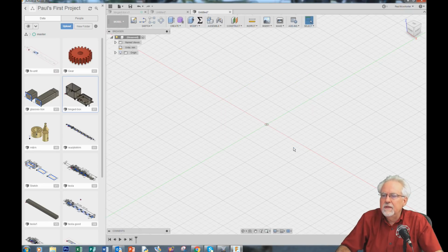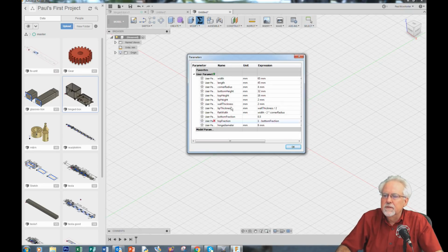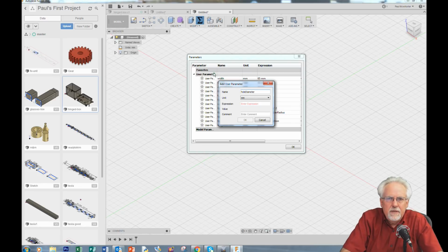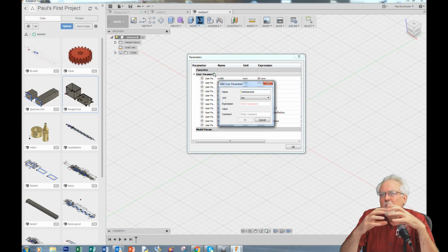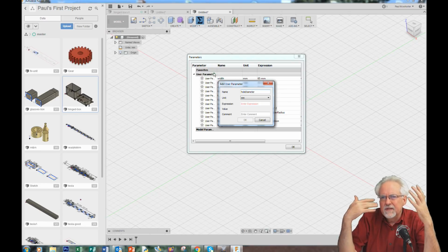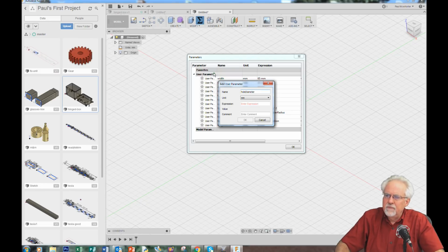All right, naming things good is very important. Shouldn't have closed that. Okay, hinge diameter is still there. Let's add another one. This time we're going to say hole diameter. Is that independent or is that dependent? Well, you can make it independent, but really if you think, you always want the hole to probably be a little bit more than half of what the whole thing is. So I'm going to set it as a dependent variable.